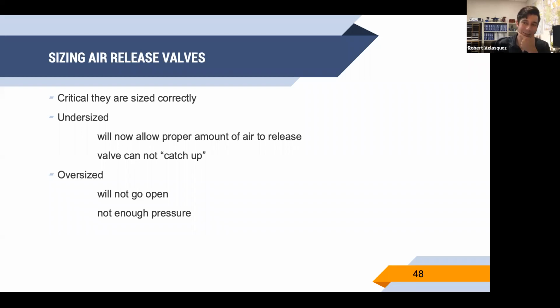On the other hand, we don't want to oversize the air valve. If we oversize an air valve, like we oversize the weight of the float and the leverage, then it won't be sensitive enough to open. It might be that the closing forces are not strong enough. In addition, another really common thing with oversized air valves is when they burp out water. They release the air, but they don't react fast enough to the water level, so each time they release air, they spray water as well.